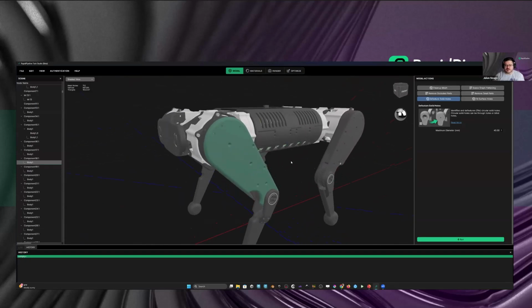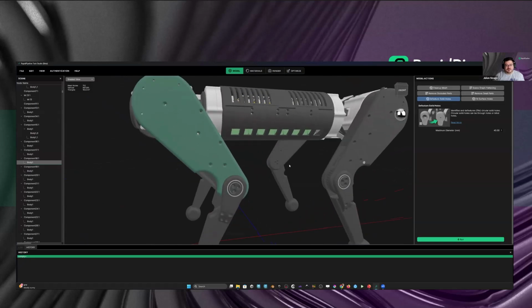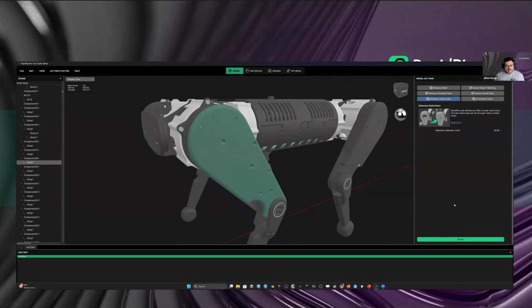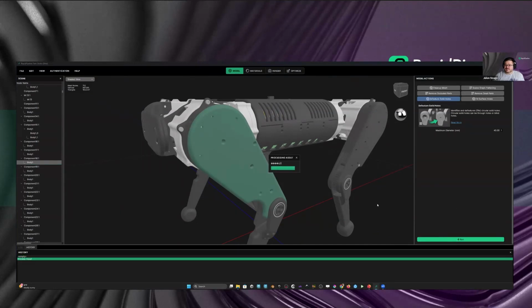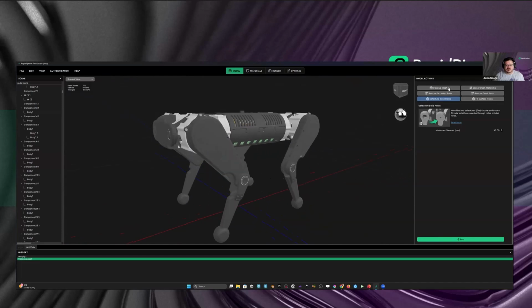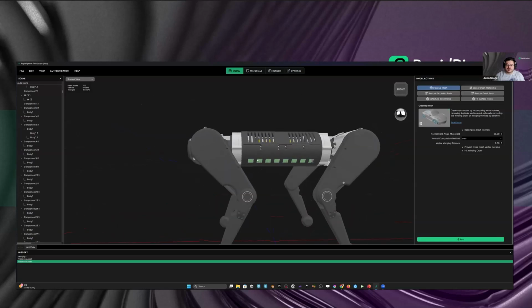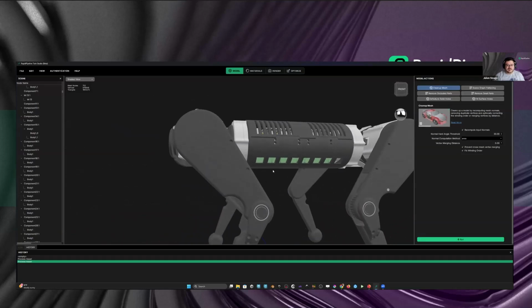What I wanted to show before is you can see we have some through holes and some bore holes. Actually, these are all through holes on our asset. With that defeaturing solid holes action, for example, we can get rid of them, as you can see here. And if we do a normal cleanup in this case, as it's a very new feature, we should run that on the whole asset and get very flat, even surfaces, which we can then use, for example, for a decimation process. As you can see here, it removed almost all the holes on the flat sides.